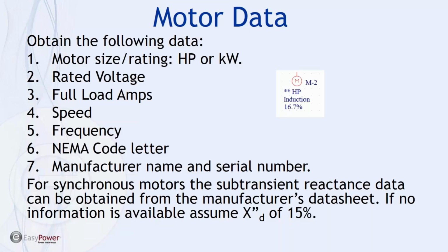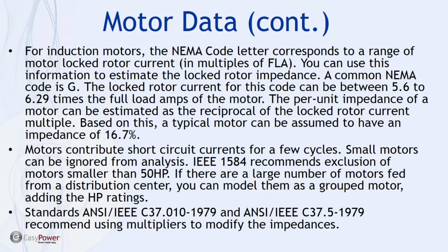And again, there's certain elements in the tool that allow us to make assumptions or look up some of these values if we know some basic information about the motor itself. And so we talked about all this. This is all based upon the IEEE standards C37.010 and C37.5 1979. Motor contributions will vary based upon what phase of starting the motor is in.